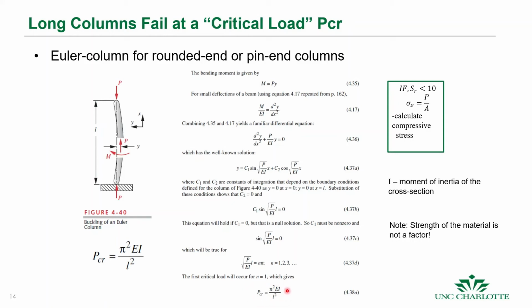Okay, so you're not going to help yourself by getting a beefier, harder material, necessarily, especially if they have the same Young's modulus. The strength of the material doesn't come in here, so don't imagine you can put a stronger material here and have less susceptibility to buckling. That would be pretty naive, because that's not the mechanism that dominates this buckling phenomenon. It has to do with the material stiffness, Young's modulus, and the geometry factors.